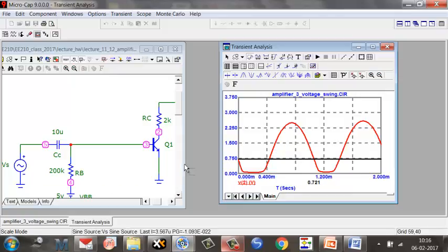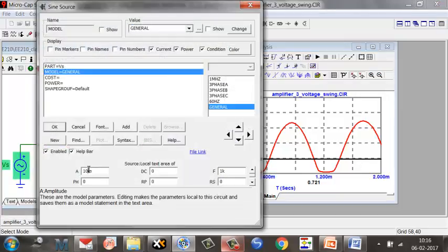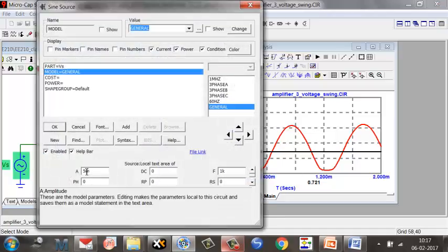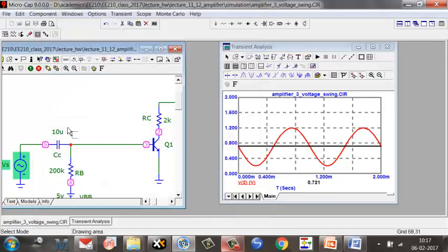Now if I reduce it, so obviously I can't get, let me reduce the voltage here. 10 millivolt is too high. Let me apply 5 millivolt. Well, you can see here, still clipping. Still it is at the edge of saturation. So you can't even apply 5 millivolt. Maybe I'll apply 3. Let's see. Okay, looks reasonable. Sinusoid. Now, we don't judge whether a sinusoid is reasonable on the basis of visual inspection.